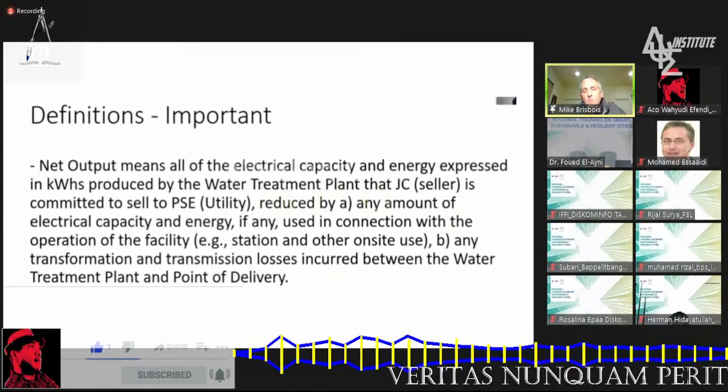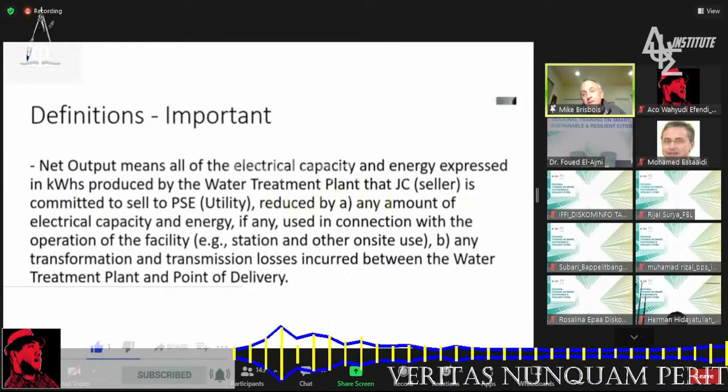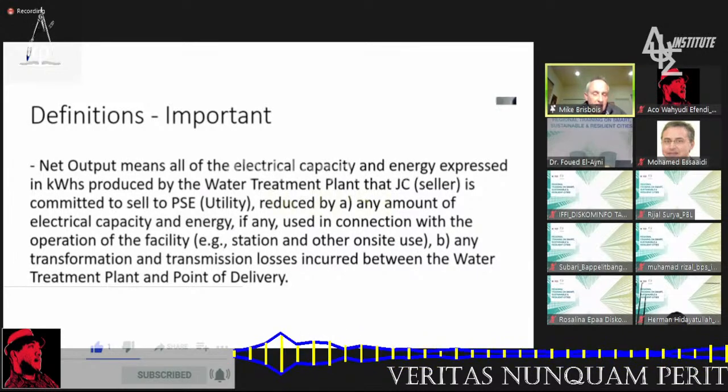so some definitions, net output. Like I mentioned, how much electrical power output the DERs, the distributed energy resources, the microgrids, the solar panels, the wind turbines are giving off. And then you have to calculate all the losses. Is there dirt? Is there sand? There's wire resistance that's taken into consideration. If you have 100% of solar, are all the solar panels working? Is there any shade? Is there any dirt on some of the panels? So that's all important criteria that you need to put into the calculations to figure out what the end result